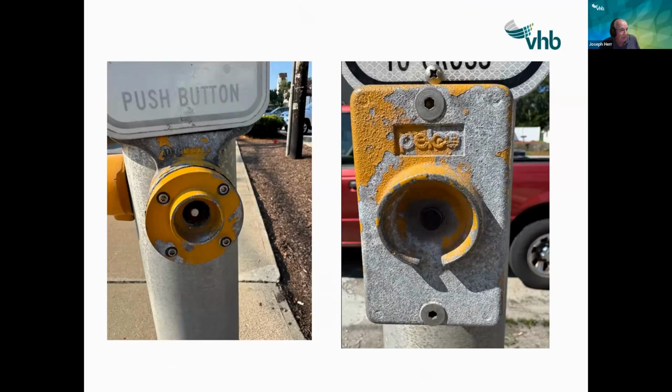I started my career in the industry back in the early 70s with the City of Boston Traffic Department. And we had small buttons like these. There was no standard on the type of buttons. Most of the buttons that were installed didn't even have signs. And some of the earlier signs that came in, we didn't have PED signals. We went to a red and yellow display for an exclusive PED, usually 12 seconds for red and yellow, and then red for 3 seconds. So it was a pretty simple type of system. You push the button, and you would get a pedestrian display on it.